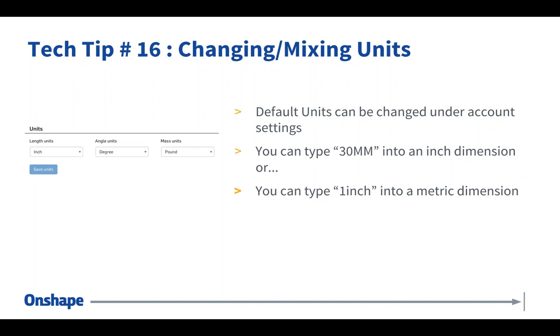So again, when you share your document, I'm going to show you this in a moment, you're sharing the entire document. If you want to share just a part or an assembly within it, it's best to use derived and insert that into a separate document.